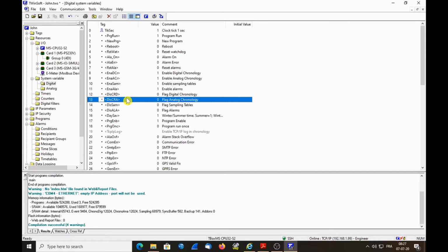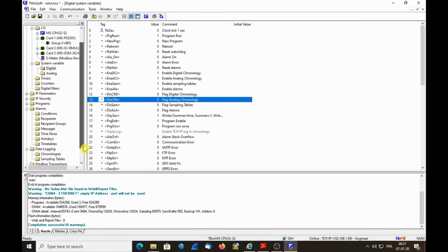So if you do a maintenance, you will stop the system, and you don't want those events to be recorded. So when you go to the site, you push on a button, maintenance button. This button will raise those two system variables, and you will do that with the programs, okay, with the PLC programming. When those tags are changed to 1, the recording will not be done.